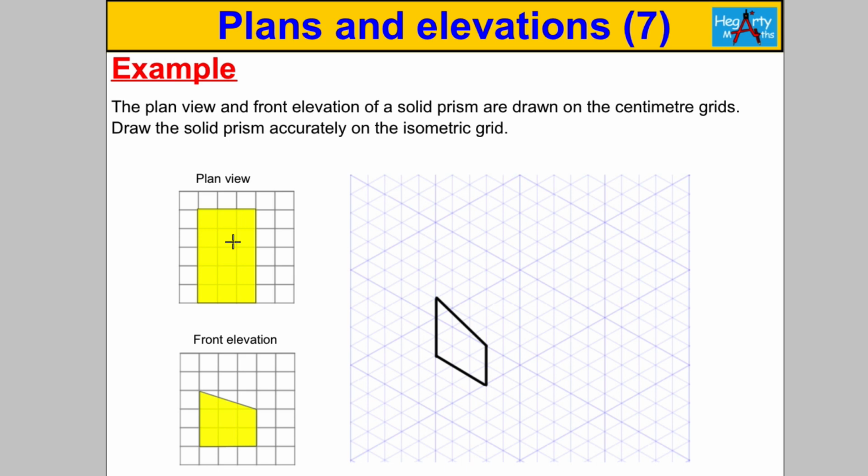And then it tells us the plan view. Now, because this thing is 3 wide, that's where that 3 is coming from. So this distance here must be how far back into the page it's going, i.e. 1, 2, 3, 4, 5. So let's go 1, 2, 3, 4, and 5, and continue here, and continue here, and join the dots together like that, and mark out that that is the front. Making it a bit neater should look something like this.